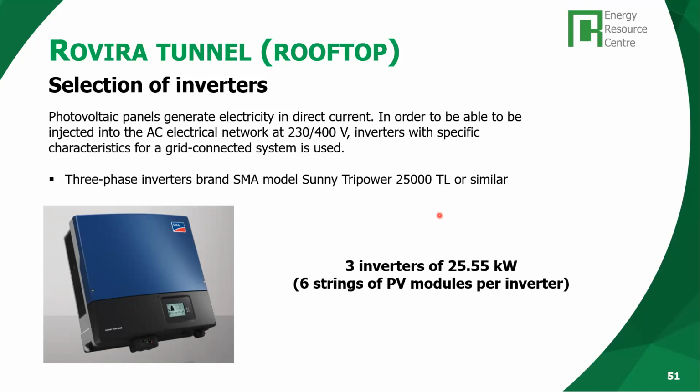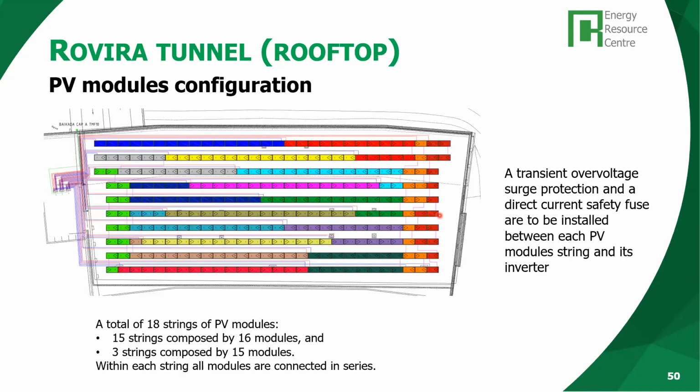And when you decide which inverter you want, you have to look at the MPPT trackers. This is one of the reasons that I chose this one, because I have a lot of flexibility to connect these strings with these 3 MPPT trackers.